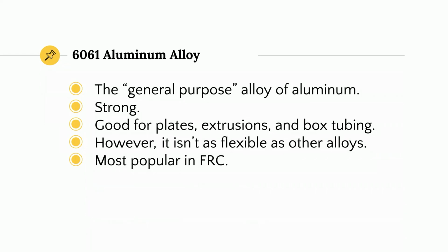However, its flaw is that it is slightly less flexible than other alloys, which is why we mostly use it for plates, extrusions, and box tubing because we don't have to bend them. This is the most popular alloy in FRC.